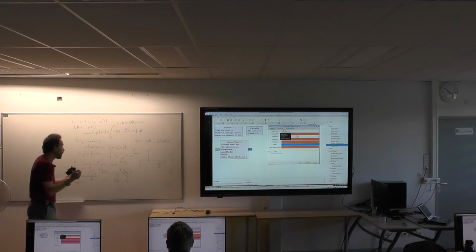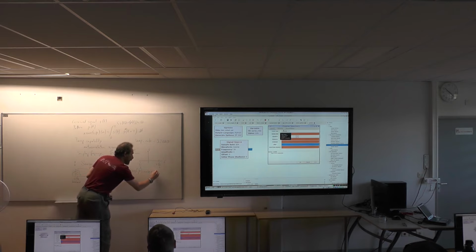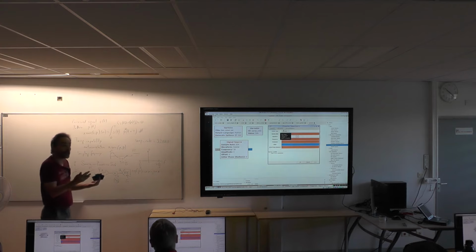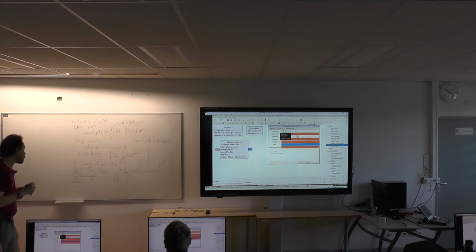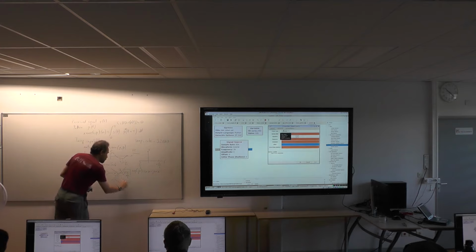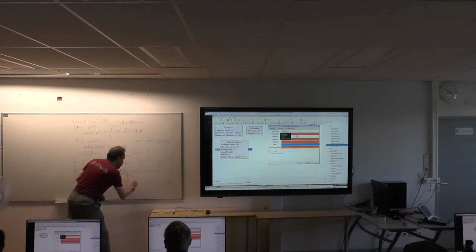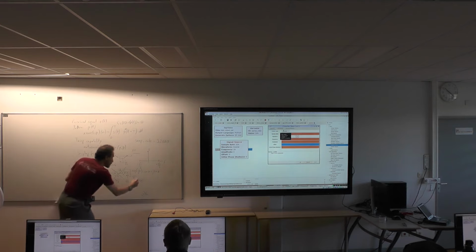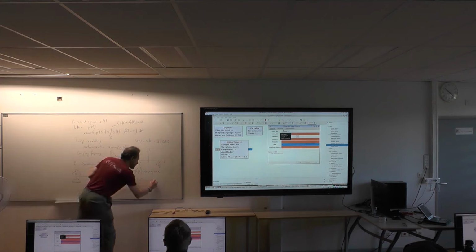So what is a complex information? Well, you know that exponential of jx is cosine of x plus j sine of x. So the imaginary part with respect to the real part is shifted by 90 degrees. The difference between a cosine and a sine is a rotation by 90 degrees. So you cannot just run a simple scheme like this one to record data and keep all the information. What you will have to do is take your antenna information, possibly amplified. As earlier, we're going to multiply with a local oscillator at a frequency Fc. And this will bring us a first piece of information which we sample at a sampling rate Fs.